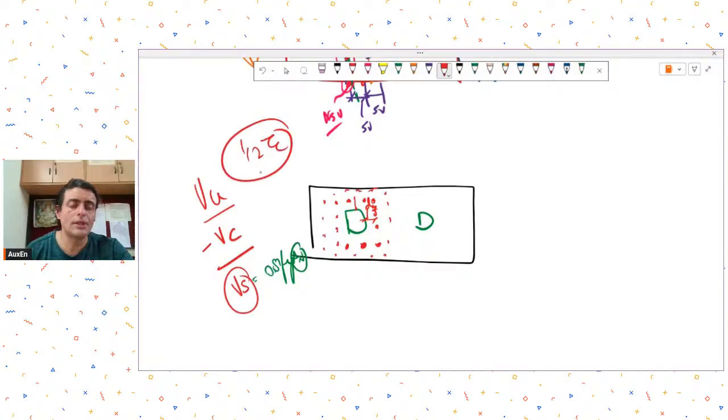You can just read the clauses given in the IS code for the continuation of punching reinforcement. It says that you have to continue providing the punching reinforcement till a distance where your punching shear stress becomes half of the concrete shear stress. So till that distance, you need to keep on providing these punching reinforcements. This is similar to what we do in a flat slab. I think, Mr. Suraj, you have already taken that course on flat slabs, where we have discussed this issue in great detail, and all the calculations also. So the same process we have to follow for foundations also.